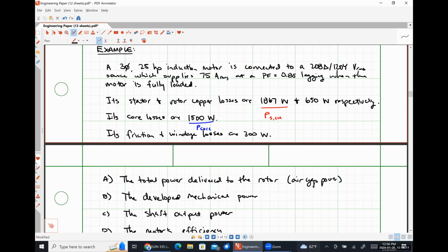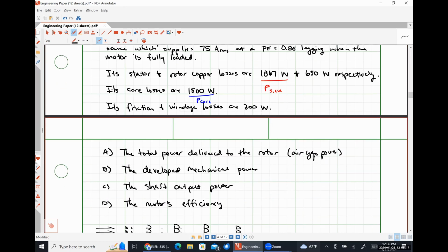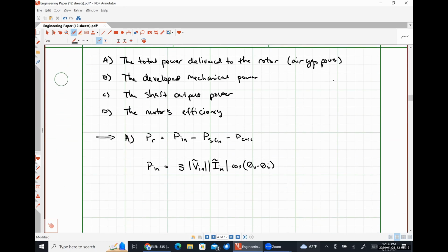If we used a phase voltage, we would have to transform that current or whatever. So that's actually going to screw with our relationship just a touch here. So instead of having 3, it'll be √3, because remember from three-phase power, that average power should be √3 line voltage, line current, cosine, phase angle, right?